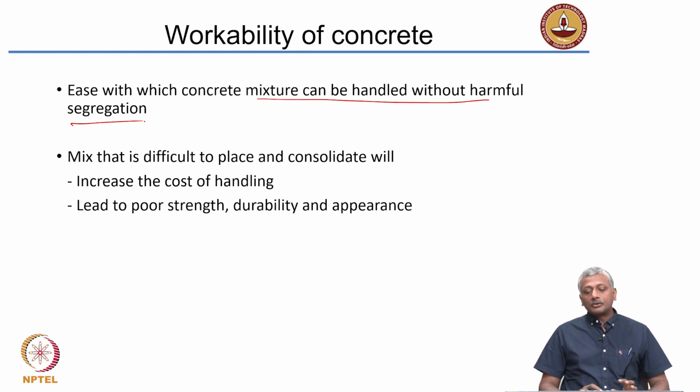Okay. Now, a mix that is difficult to place and consolidate will increase the cost of handling and also lead to a poor performance in terms of strength, durability and appearance. So, you need to provide concrete of the right level of workability. It is very important that you do so.